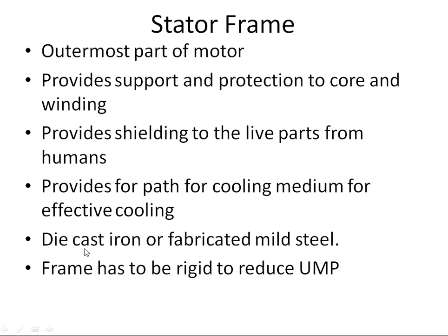The stator frame is basically made up of cast iron. So it is die-cast using cast iron, or it can be made up of mild steel with fabrication, either riveted or welded. For large size motors we use fabrication, whereas for small motors a single casting of iron will be sufficient for the frame.